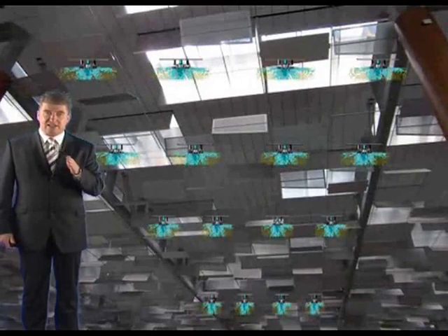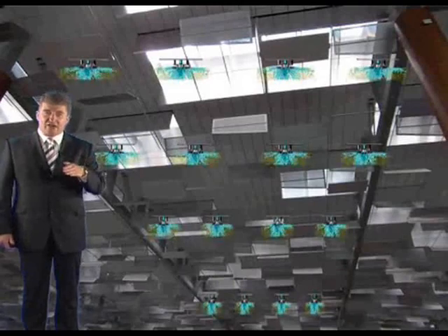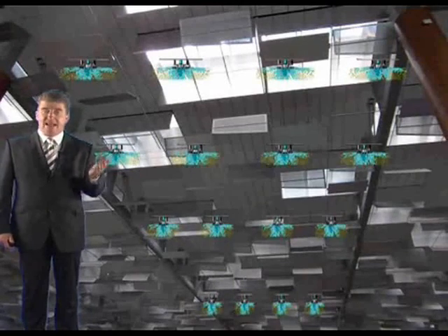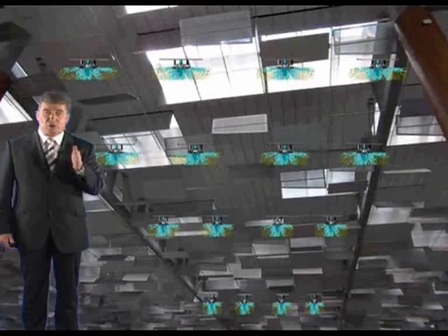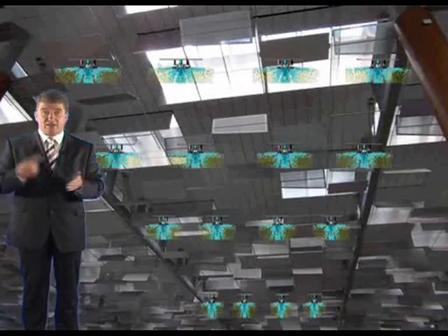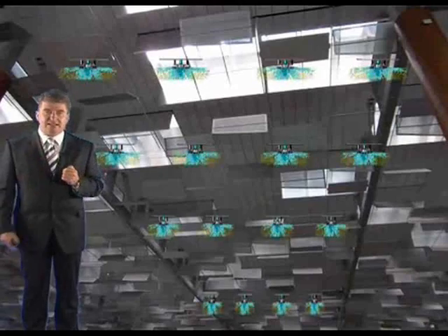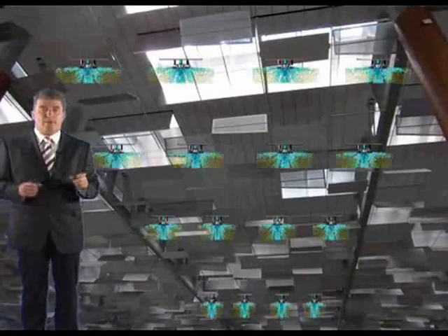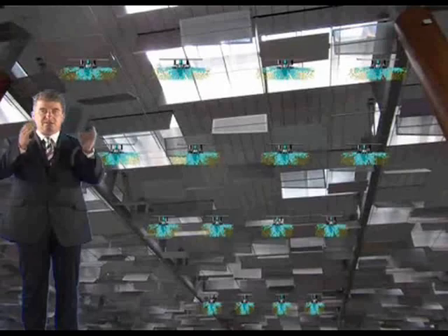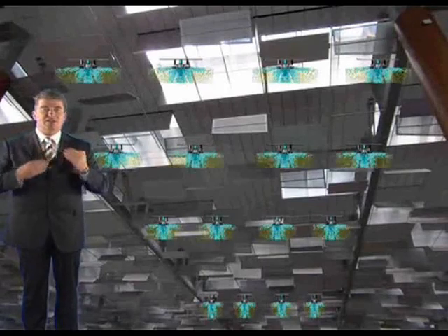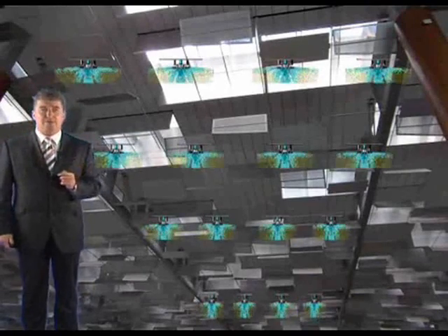Where sprinklers successfully contain a fire, you could argue that ventilation may not be needed except for post-fire smoke clearance. You know, after the fire brigade got there, they come and get the smoke out. Now, these are the issues that must be considered by the designer. But as I said, there's not a problem with having ventilation systems and sprinklers working together. Generally, there's no problems. Now, that covers the introduction.